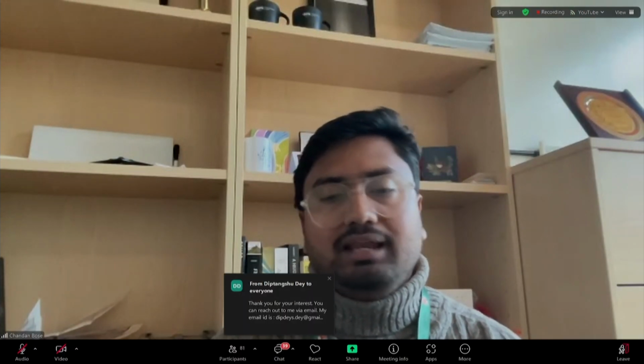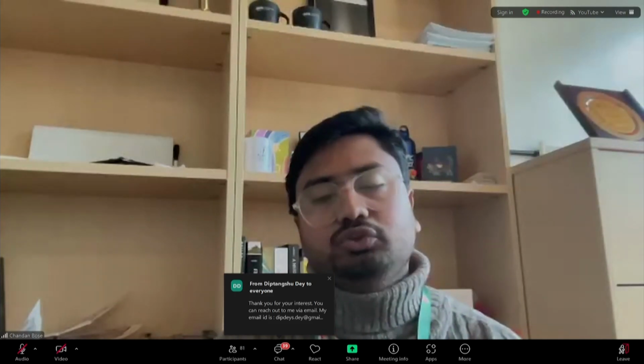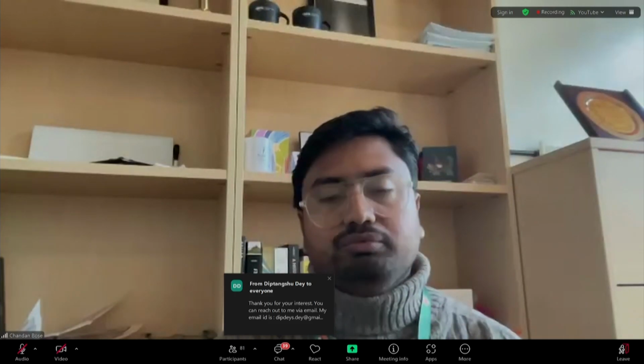Can I add a point here? Sorry, I'm Chandan. So basically, I just wanted to add that if you have already used ANSYS and you know how to mesh in ANSYS Fluent or any other sophisticated meshing tools such as Pointwise and other software, you can always import your mesh into OpenFOAM. That's one very useful feature of OpenFOAM, that OpenFOAM allows any third party meshing software's exported mesh to be imported as polyMesh within OpenFOAM.